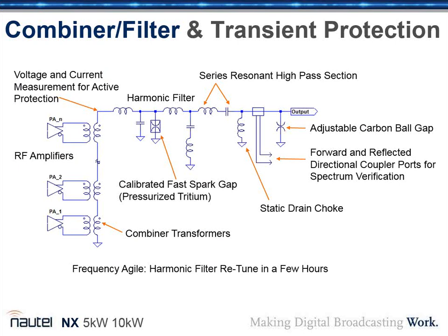It's an interesting point because what I have learned over the years is that the typical failure mode of an AM transmitter, particularly a Class D H bridge, is that it's the power in the power supply that destroys the transistors more often than the lightning itself. The lightning creates a DC short at the output of the transmitter because the ball gaps and things like that short. But in those H bridges, you destroy the symmetry and the switching synchronization, and you start drawing current from the 400 volt supply straight on down to ground, destroying those transistors in vertical pairs.